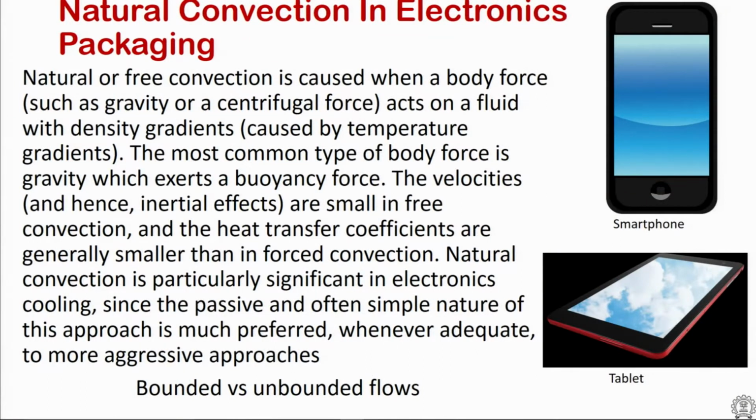Modern day electronic devices like smartphones and tablets often have their design evolution or high power performance restricted by thermal design and power delivery. And thermal design is such that for smartphones, since we hold the phone and talk to a person, the skin of the phone should not exceed a certain temperature. That is roughly about 41 to 45 degrees Celsius, depending on the manufacturer.